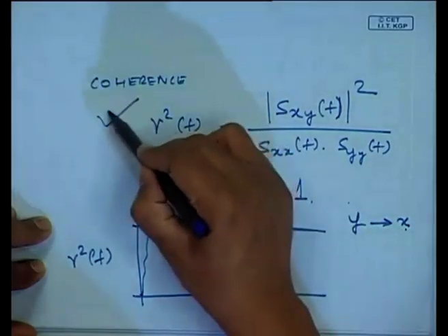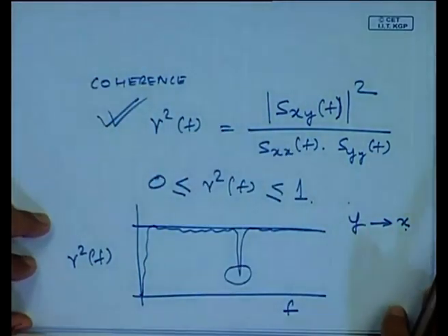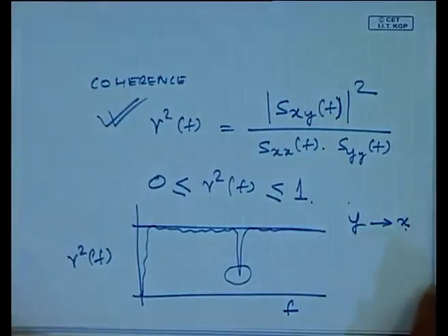This can be found out by this coherence. And in machinery condition monitoring, when we measure signals from machines, we will be trying to find out the coherence between the input and the output, between two transducer locations, whether one is causing the other. And this is a very powerful way of diagnosing or finding the source of a fault.